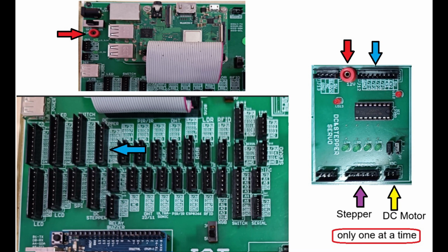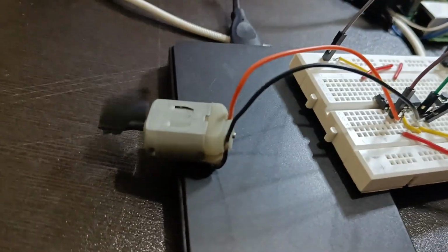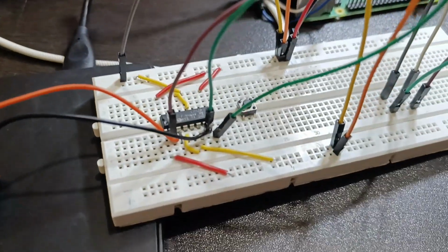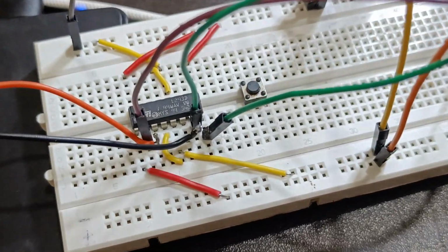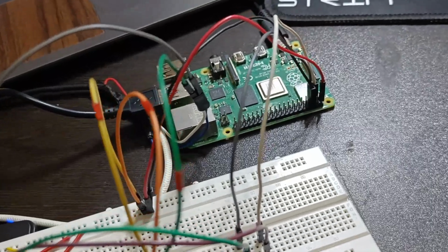So these are the pinouts. You need to connect this accordingly, color coded. Also make sure to connect the 12 volt supply. It won't run if you are not connecting the 12 volts through the jumper. There are jumpers available, just ask. Okay, here this is my setup.